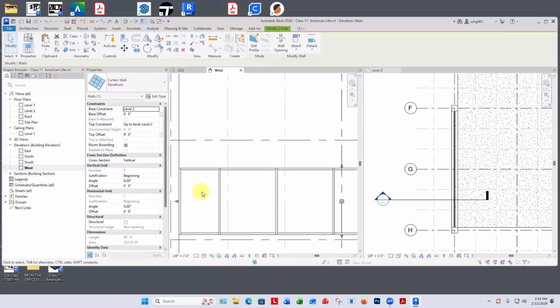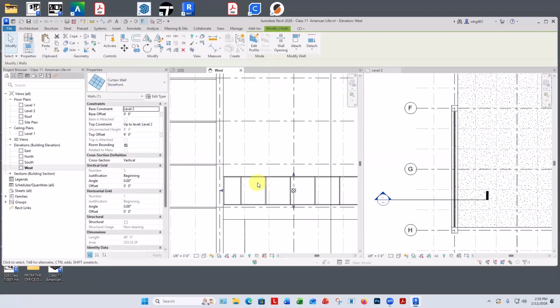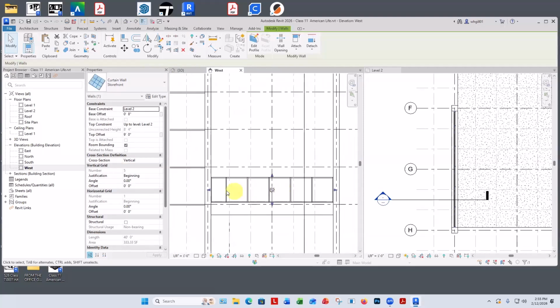So now we're there. And then the position of these, you'll see, is it just starts at this end and goes 7 feet, 7 feet, 7 feet, 7 feet. What we want to do is actually have this on the center and have these be 7 feet and have the 2 on the ends be slightly less. So the spacing is set in the type properties. Where they actually are, the justification of those within the space is set in the object itself. So the justification, I'll say center.